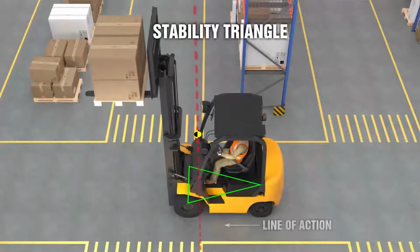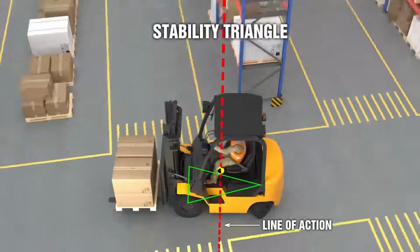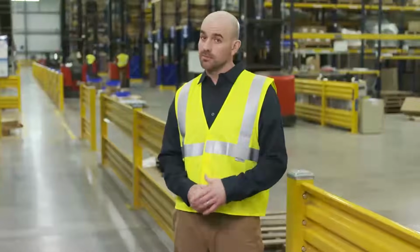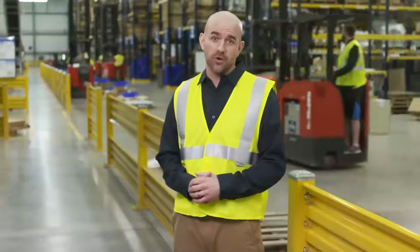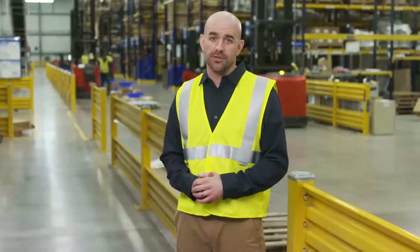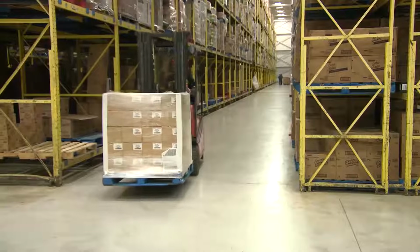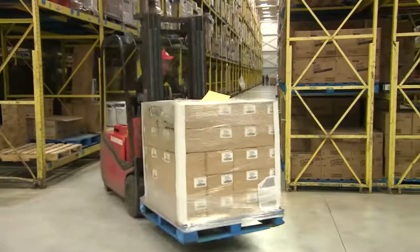There's also what's called the line of action, which travels up and down with the load. It's a lot to consider. But that's why you need to understand your load and take care when moving with it. Anytime you shift outside the stability triangle, you're in danger of tipping over. Even an unloaded forklift can tip from the weight of its counterbalance, so don't rush to your next destination and never engage in horseplay.